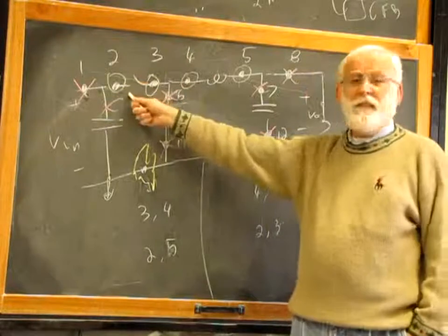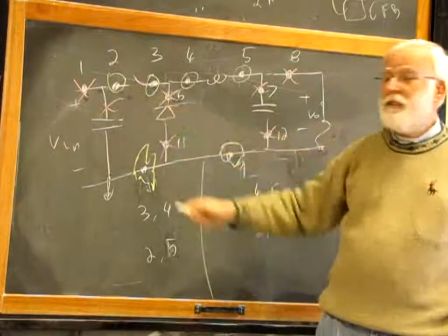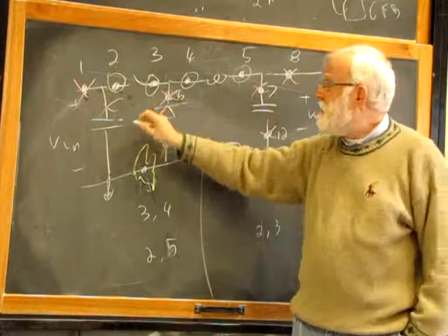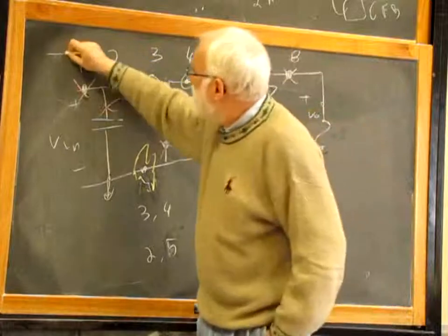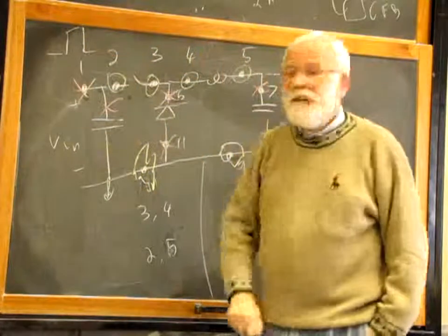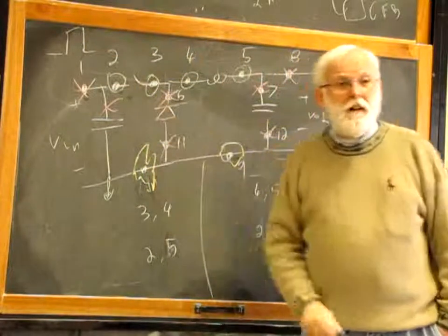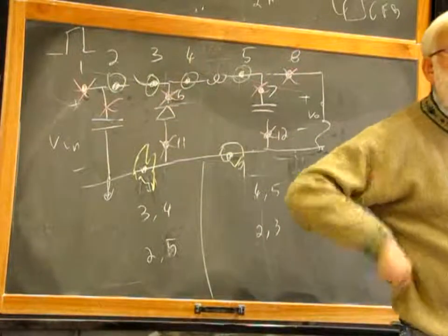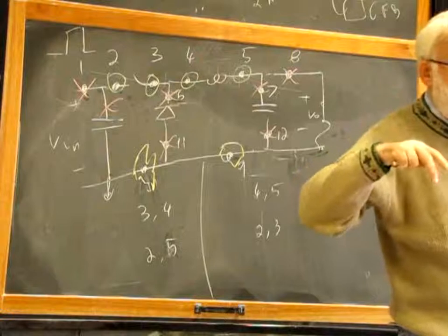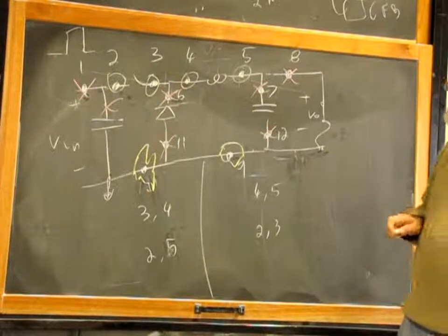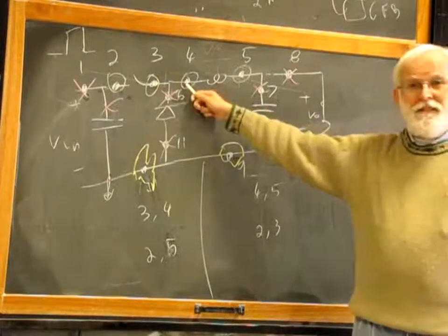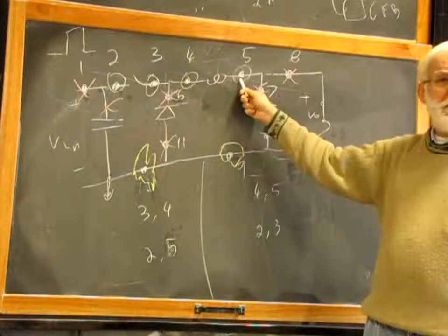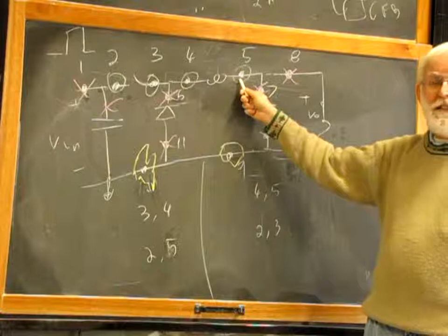DC voltage here, you have big DC voltage. What about the voltage over here? Just observe that current over here is absolutely the same. The current in 2 and 3 is something like this. What about the voltage in 3? Section 3. Square wave. What about the voltage in 4? Square wave. What about the voltage in 5? More like DC. This is a DC.